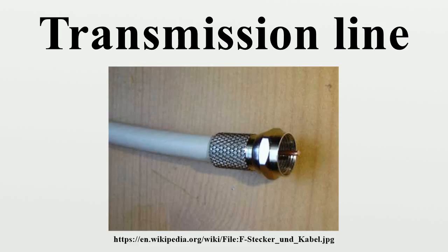Because the conductors are always the same distance from each other, crosstalk is reduced relative to cables with two separate twisted pairs. The combined benefits of twisting, differential signaling, and quadrupole pattern give outstanding noise immunity, especially advantageous for low signal level applications such as long microphone cables, even when installed very close to a power cable.